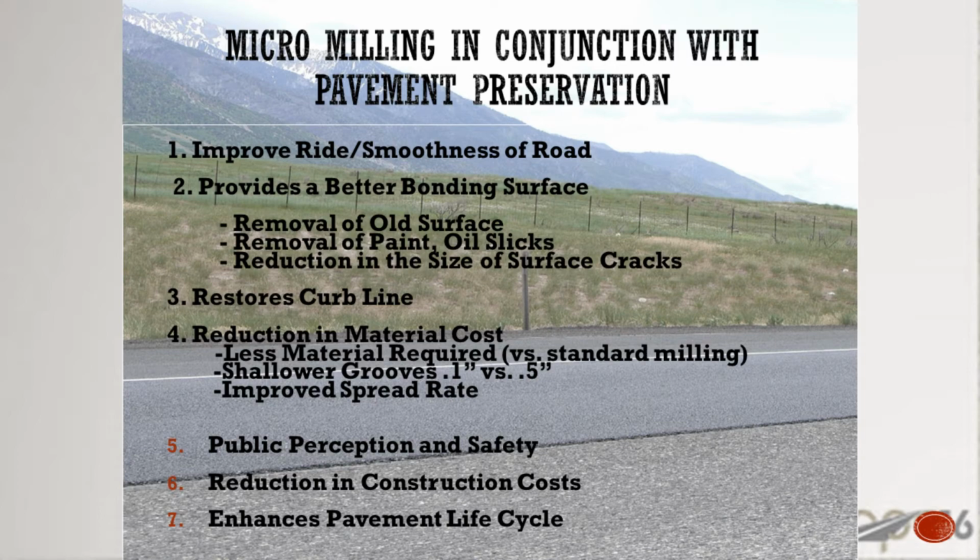When comparing to standard milling, you're no longer having to fill in a bunch of grooves. You're filling in 1/10 of an inch grooves, 2/10 of an inch grooves instead of 1/2 inch grooves. Improves spread rate for your tack coats. Also, public perception. All of a sudden, you're riding on this road and it's smooth. People will notice, and also it's safety. If it's nice and smooth, if they're running on a milled surface, you minimize those concerns.